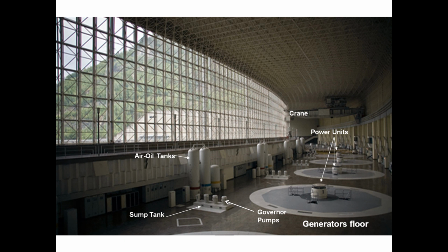But there's a risk. When water is flowing really fast, the pressure of the water decreases. And you're going to learn about that when we start discussing the Bernoulli equation in Chapter 4, more of the reason why the pressure goes down. But what you should know for now is that when water is moving quickly through a confined space, the pressure decreases. And the pressure can decrease so much that it falls below the vapor pressure of the fluid. And so if the pressure surrounding the fluid is less than the vapor pressure, it begins to boil.